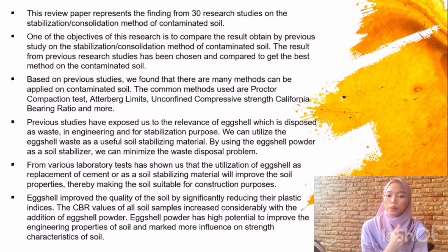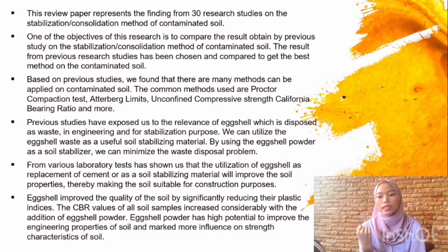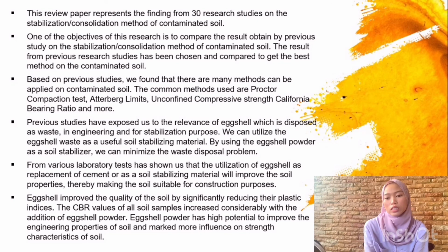Various laboratory tests have shown us that the utilization of eggshell as a replacement of cement or as a soil stabilizing material will improve the soil properties, thereby making the soil suitable for construction purposes. Eggshell improves the quality of soil by significantly reducing the plasticity indices.